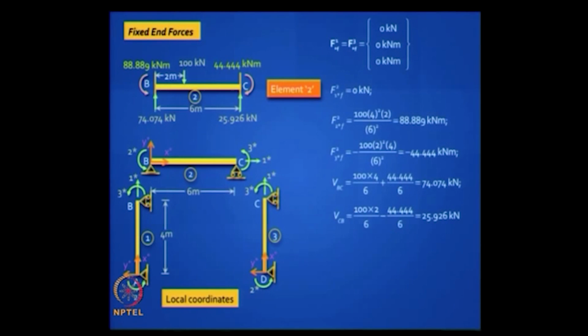We've done this calculation in the conventional stiffness method, so I won't repeat it, but it's important to work out those vertical reactions. In the conventional stiffness method, those vertical reactions went into your fixed end force vector because you had some coordinates there, you had 6 degrees of freedom. Here you have only 3 degrees of freedom, but you still need to work out the vertical reactions. Why? Why do you need the vertical reactions? Those will be 1 star and 1 star in the first and third.